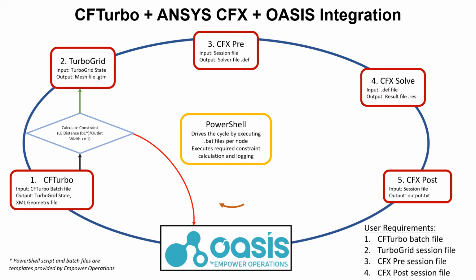The third node sets the domains, interfaces, and boundary conditions as per the ANSYS CFX pre-session file and outputs the CFX solver input file. The fourth node executes the CFX solver, and lastly the CFX post-session outputs impeller efficiency and head values, next to the earlier calculated geometric constraint.